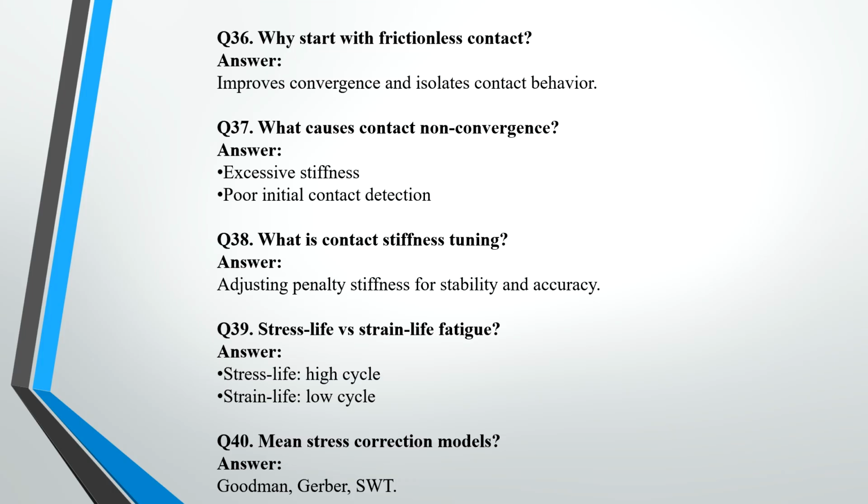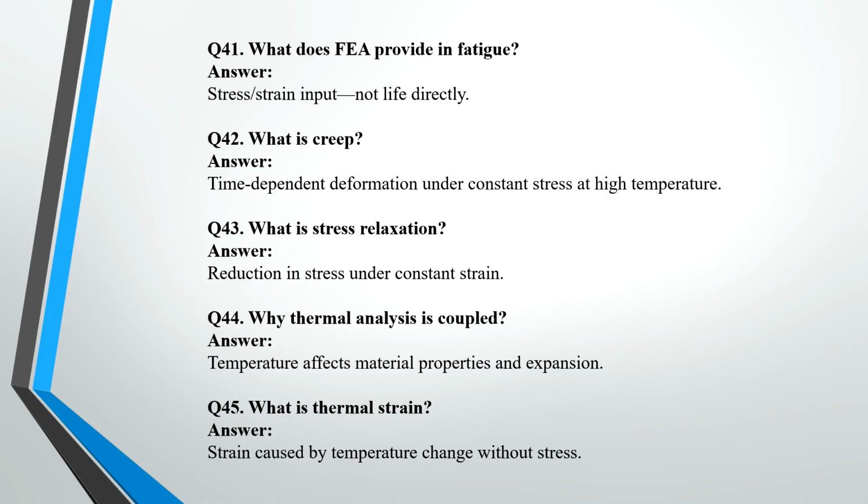There are three: Goodman, Gerber, and SWT. What does FEA provide in fatigue? The input we give is stress and strain, not life directly, because we won't get the life from FEA, but we get the stress and strain response.